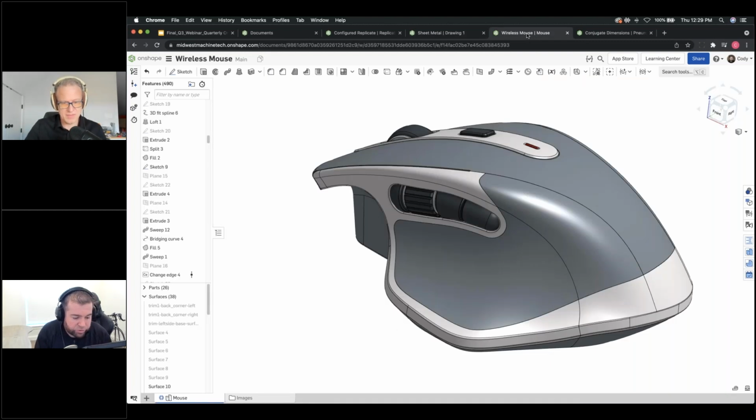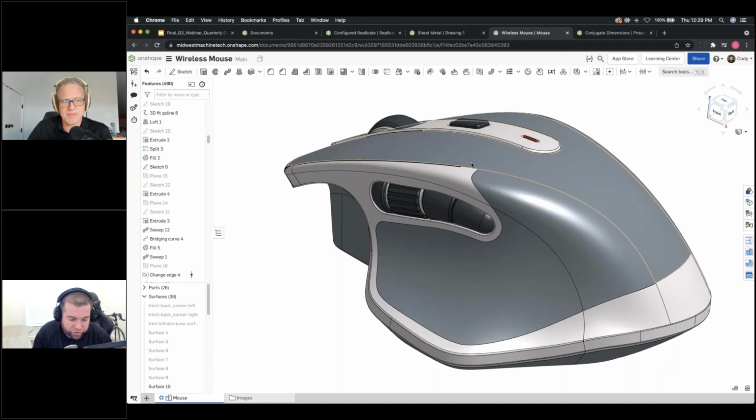So my next feature is one of my personal favorite modeling features, surface modeling especially. This is one that so many users have requested. If you do any kind of surface modeling, you'll know where this is useful and where it's applicable. It's referred to as ruled surface, and it's essentially anytime you need to create a ruled or extended surface off of an edge that's normal to the direction of that forming edge, that curve.